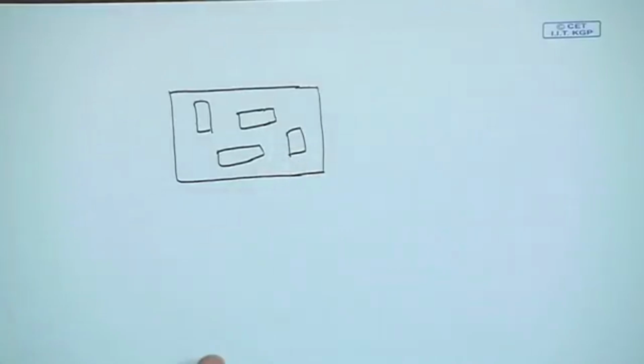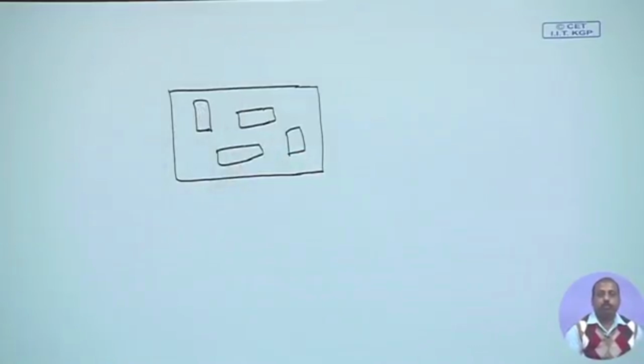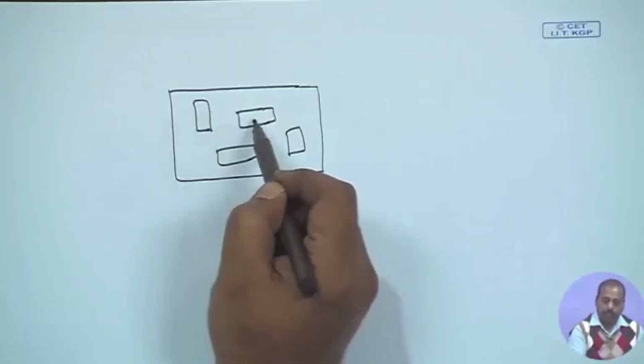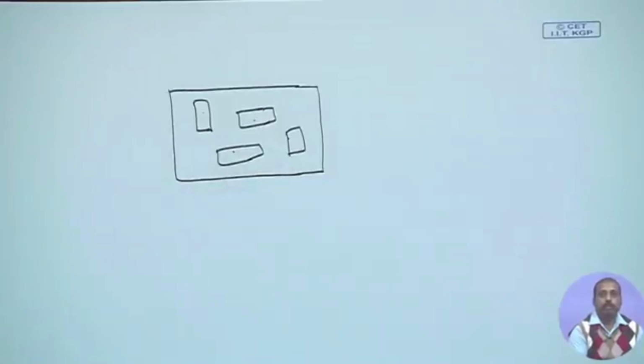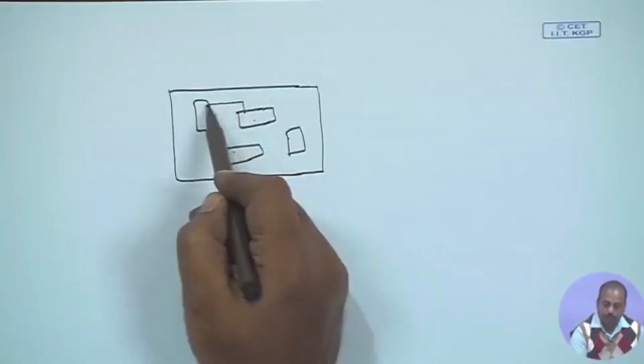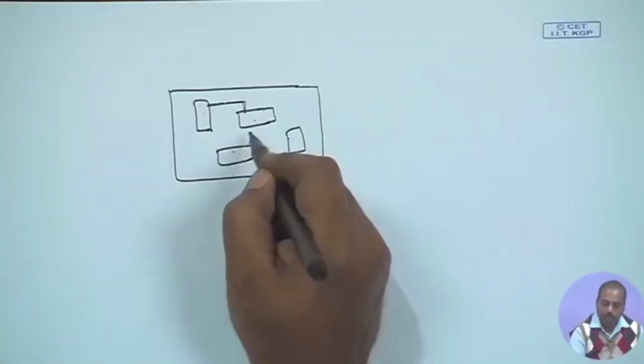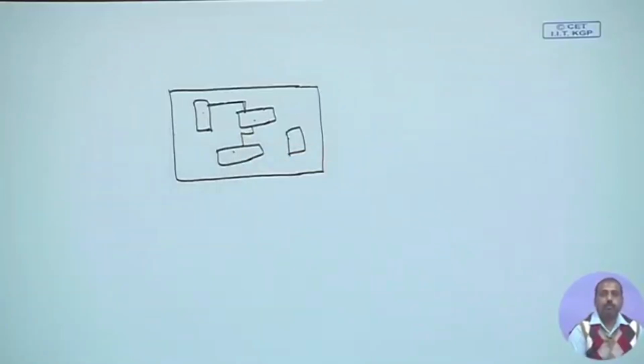For testing purposes, these chips are shipped into the market by the vendor, and they have done their own testing. So, naturally we can be confident about their correctness. These chips may be assumed to be correct, but what we need to test is the interconnect between the chips. This interconnect is a copper line running between two chips. So, that line has to be tested. Similarly, this may be another copper line running between the chips. So, that has to be tested. This way we need to test only the individual interconnects.